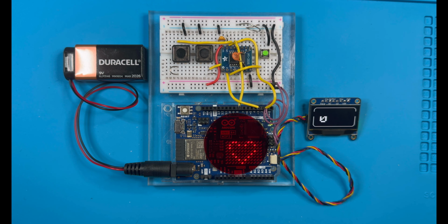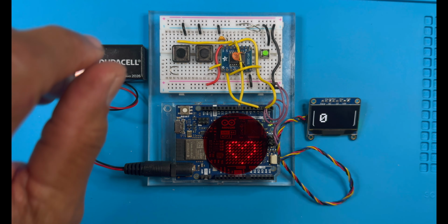Now let's take a look at our bounce eliminator, the MC14490. We have a capacitor used on this particular version, a 1 nanofarad. It'll give us a 2 millisecond window. And if you want to go a little higher, you can go up to about 9 milliseconds with a 4.7 nanofarad. But here we're starting out with a 1 nanofarad. It'll give us a 2 millisecond switch bounce window. So we'll start off with our count.